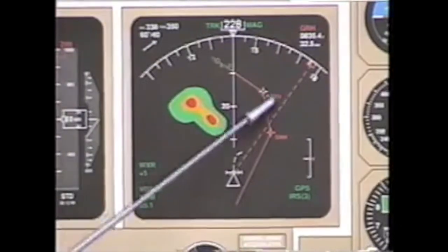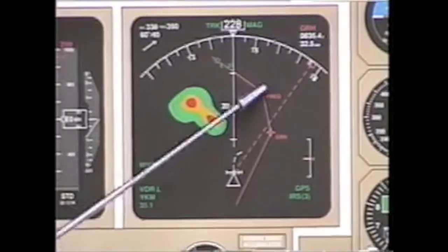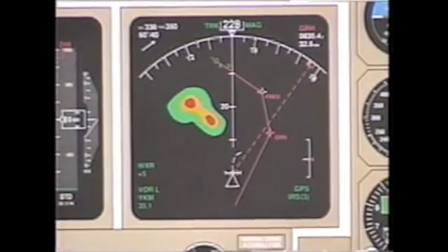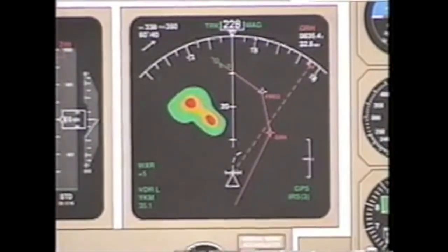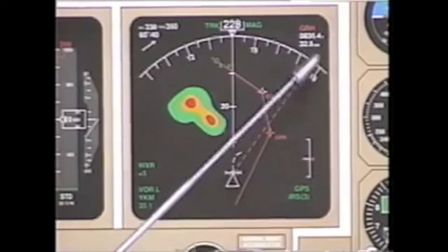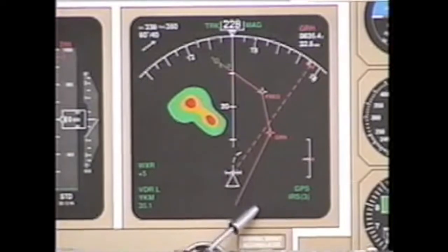The route line on your nav display, it is possible to have 4 different route lines displayed. A solid magenta line is the active route, be it route 1 or route 2. A dashed white line is a modification to this active route. A dashed blue line would appear for the inactive route, and a dashed magenta line, not to be confused with this dashed magenta line that goes out to the heading bug, the other dashed magenta line is an offset.